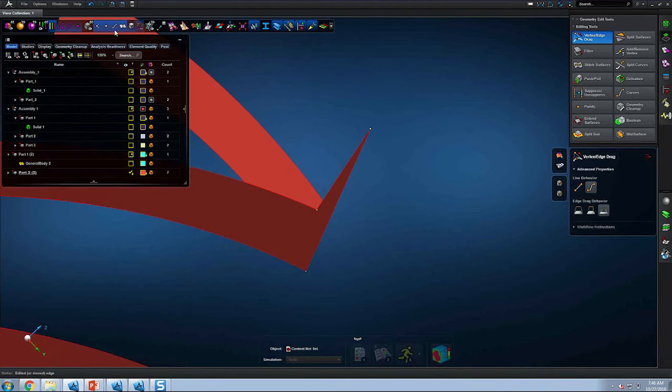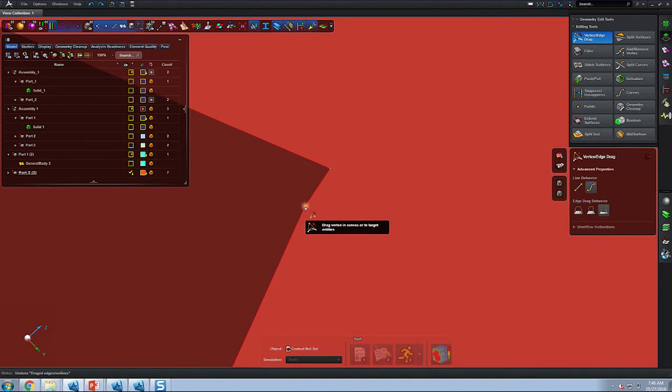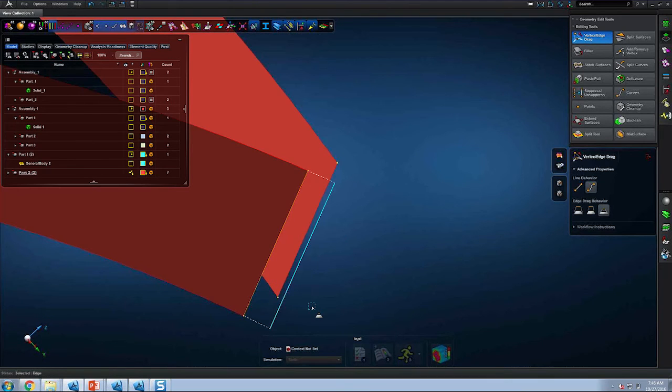I create this large spike in the model. The reason for that is that there's an extra vertex here. There are a number of ways we can address this. We can take the vertex and move it anywhere that we would like. Here's an example. I want to move it there. And then I can perform my operations as I did a moment ago.